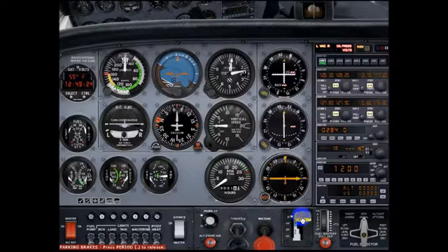And then we have a flap switch. The flaps, again, from my private pilot videos, you know what flaps are. But we can set the wing flaps for 10, 20, and 30 degrees. And then we have a pitch indicator, and I'm just pressing that, and I'm rotating this down to the takeoff position. You see TO, that is the takeoff position, not Terrell Owens.